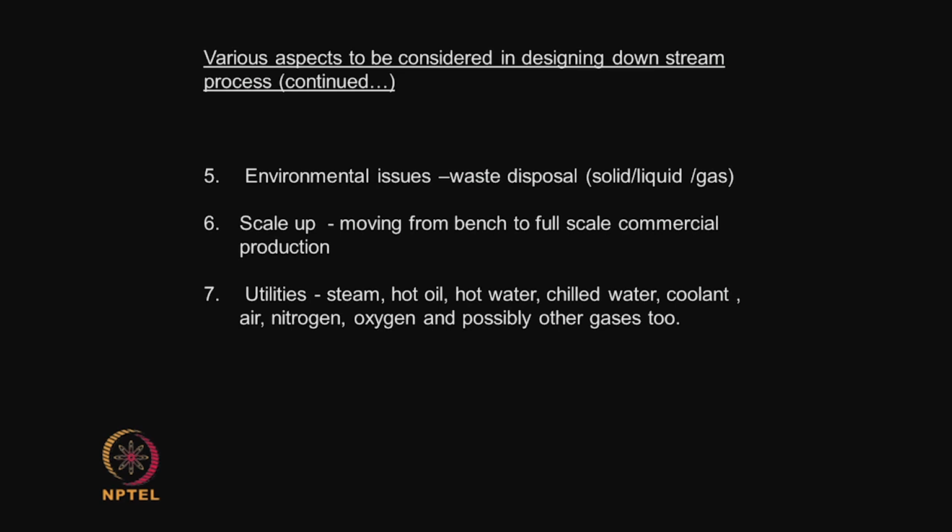If I am using 2 different solvents, then I am in big trouble, because I will be mixing those solvents and then recovering each of the solvents independently or individually is going to be very difficult. So, try to use less number of solvents instead of mixing solvents. Gas, can I just vent the gas out?